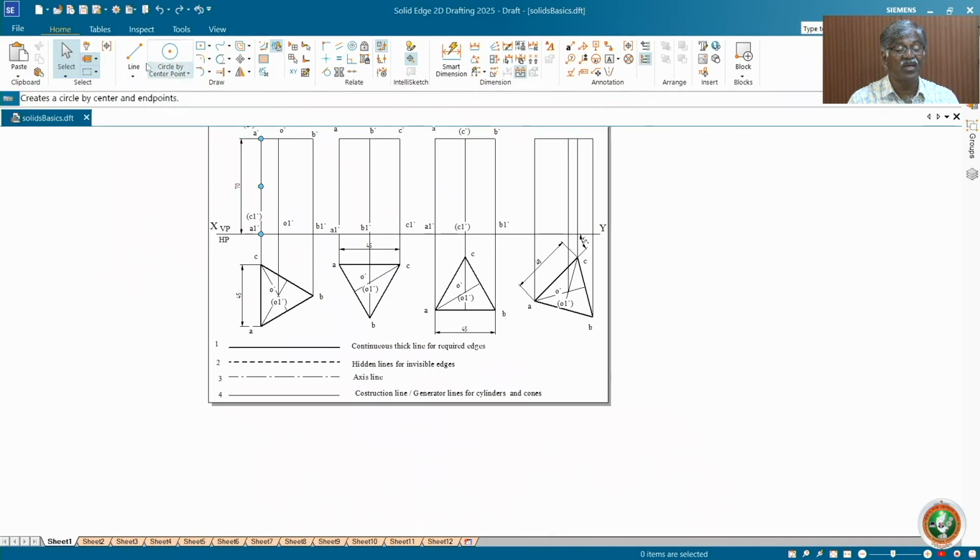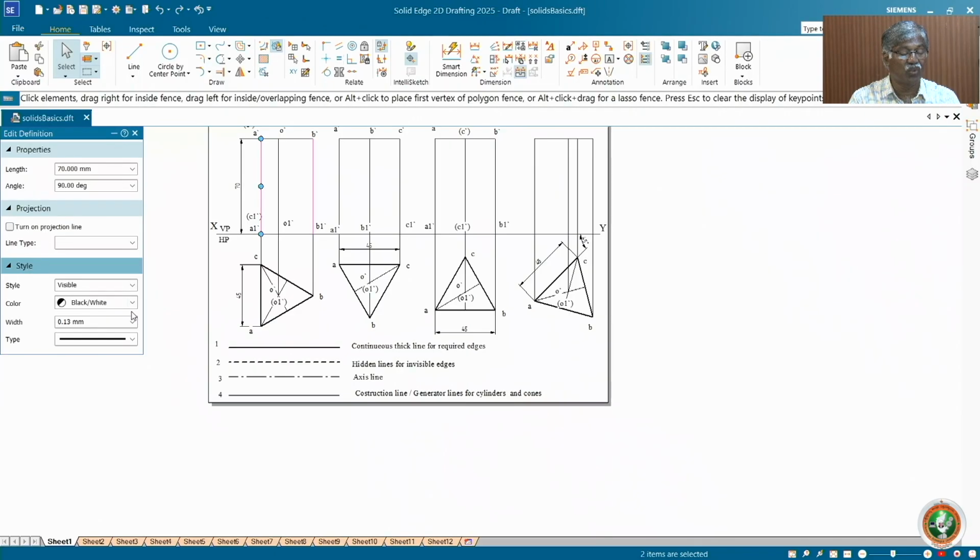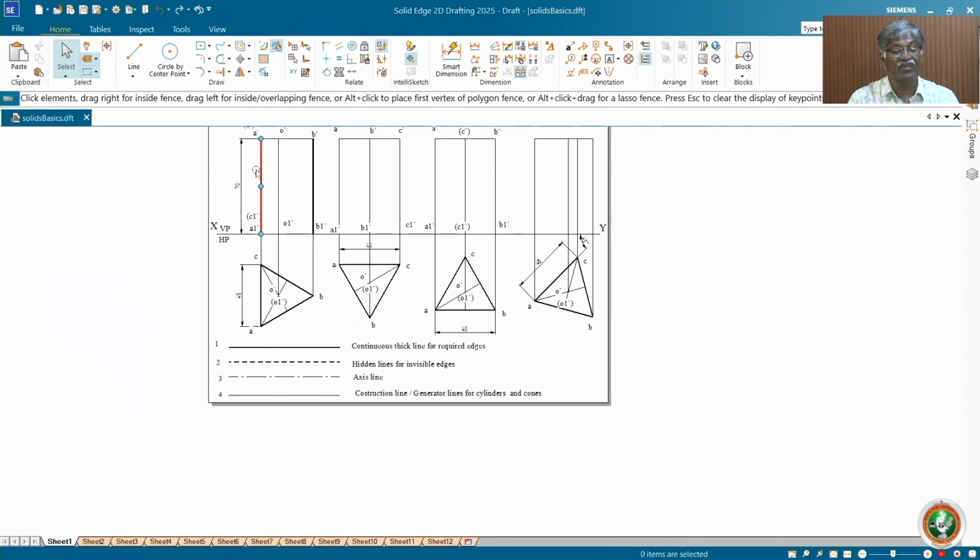So what you do is you dark that, you select, and I have made all light, thin line. Now let us make either thick line or dotted line here. So you select this and make dark. Purposefully I take a little bit more thickness, actually it must be 0.5, I will take this 1 for understanding purpose. Okay. So this is to be darkened.